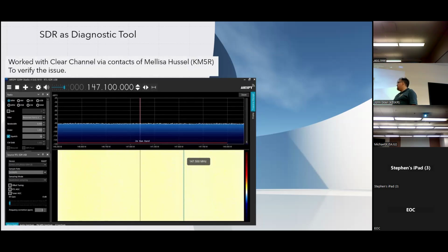They did some tuning remotely. I'm not exactly sure what they did. It's an LED billboard, and I have found issues in the 2-meter frequency. There are other LED billboards in this area throwing off spurs. The Hurst Library is one of them. Fortunately, that one's low enough to the ground that it's not causing too much problem with radio signals, but it lights up the Kraken every time I fire it up. The one at the public library is the same. They all do. I don't know if it's in the LED panels themselves or the power regulation on them. Not really, but LED billboards throw off all kinds of spurs in the 2-meter range.